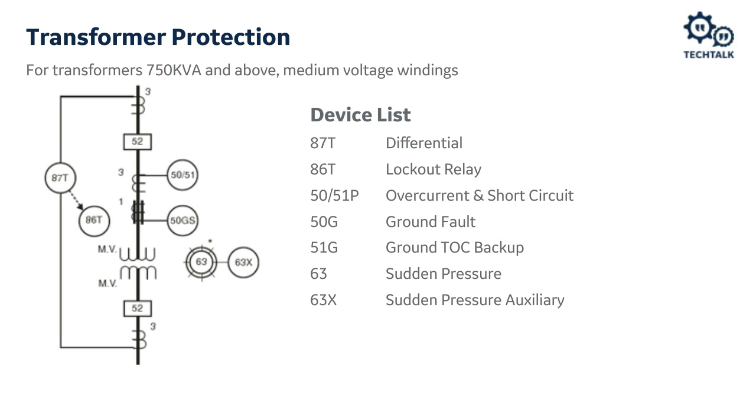And then our 50/51 overcurrent protection, like we saw before, would be more like a secondary scheme and for ground fault protection. We also note the 63 sudden pressure relay you see here, but notice how it's shown as a separate device on the single line. Again, this would be a completely separate specialized device from the main protection relay.